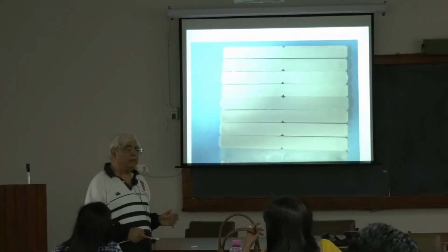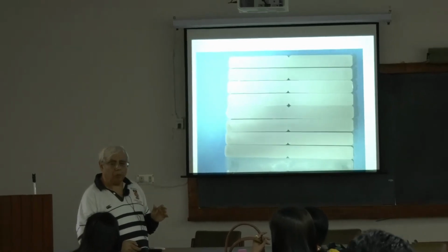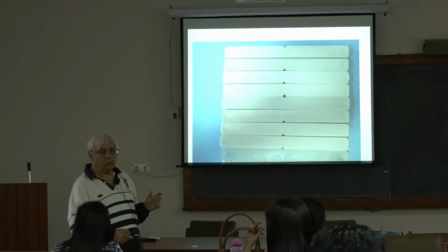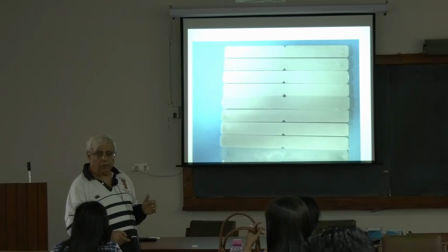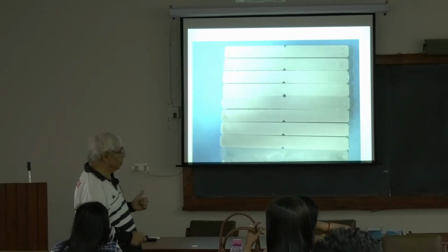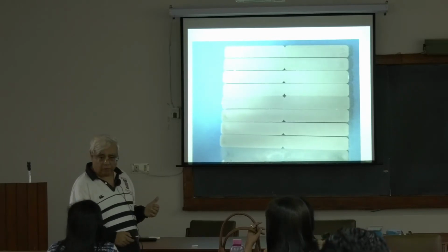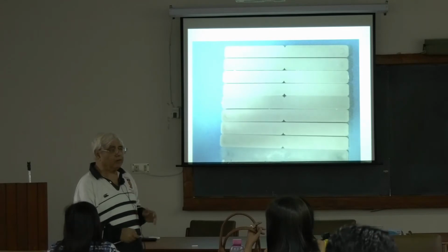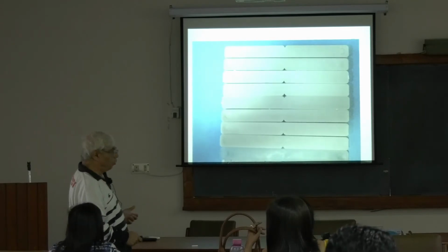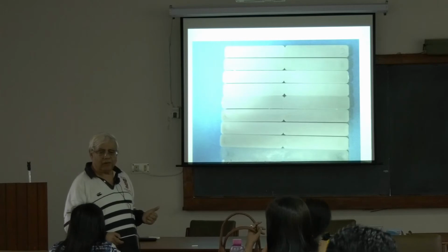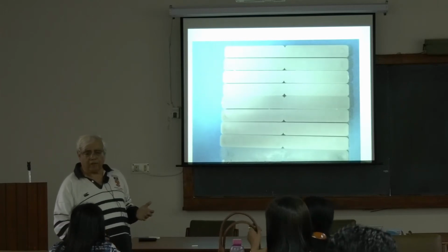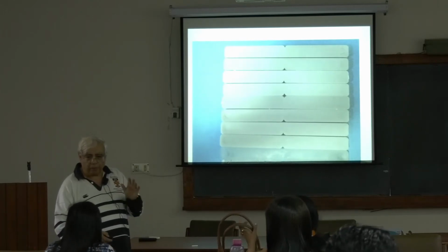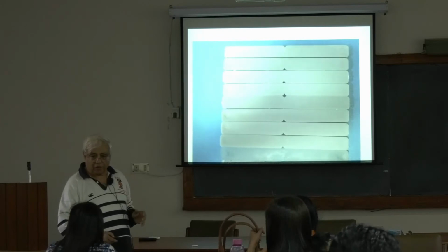Yes, it depends. So you also do tensile modulus. Then you also look at the strain to failure. And also you look at the impact. Impact is important. Compression test sometimes is much better. So from my experience, tensile test is not always a very valuable thing. Just don't only depend on that. Go for the modulus and other things. Okay.